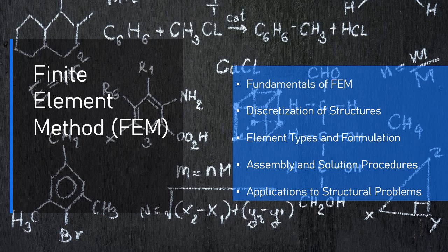4.1. Assembly of the global system. 1. Nodal connectivity and global degrees of freedom, DOF. The first step in the assembly process is to determine the global degrees of freedom, DOF, of the system. The DOF corresponds to the number of unknowns, typically displacements or rotations, that need to be solved for at each node. For a 1D truss element, the DOF at each node is typically a single displacement along the axial direction.